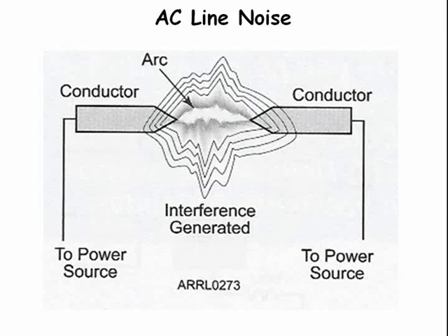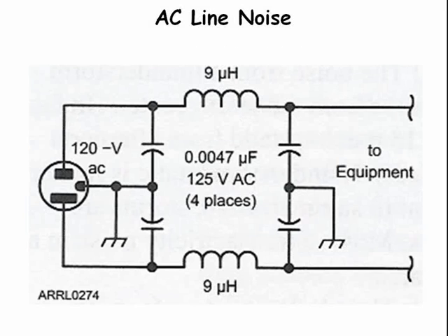Electrical line noise can be particularly troublesome. It can cover up all but the very strongest of signals. Arc welding in your area can be particularly troublesome. A brute force AC line filter in series with the power leads will help block the noise from being conducted along the power wiring.